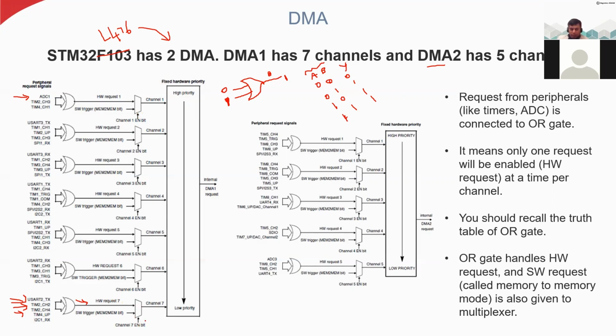So for example, here I set up the enable bits as 0, 0, 0, 0, 0, and so on. Then this mux is off, so we don't get anything at the output of this mux. But if I set up the enable bit as 1 here, then I can get the output from only this mux, and I am giving it here.